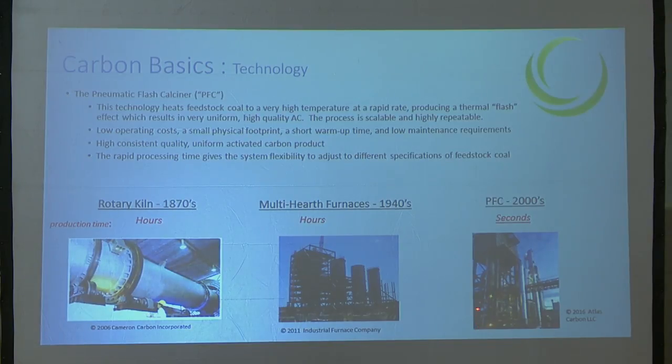It takes about 2.5 seconds from the time coal enters the reactor to the time it leaves at the top. Very fast. We have about 2 to 2.5 hours of warm-up time, and then we're ready to make carbon. The advantage of that quick warm-up, as well as the variability, is that we can vary different things throughout our reaction train and have quick response time, whether that's temperature, water inputs, steam inputs, or air-gas ratio. We can vary a lot of things and get instant response, and not have to wait hours to see what that carbon looks like.